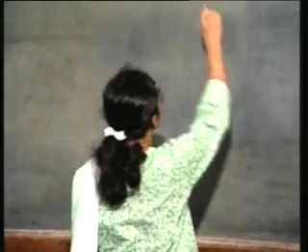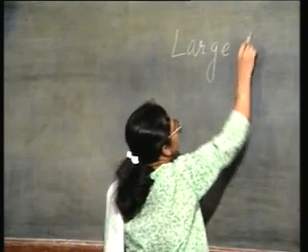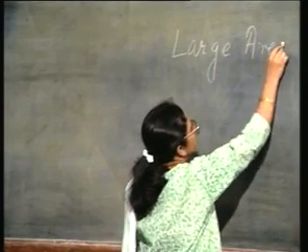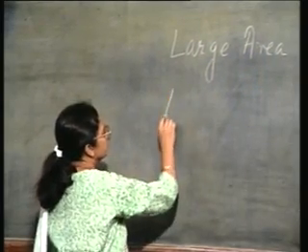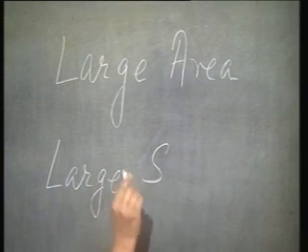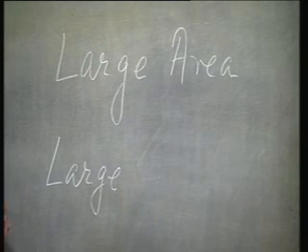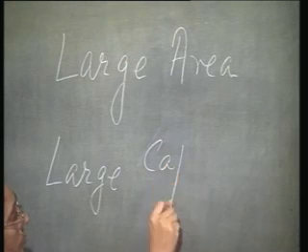So, you see basically the PN junction isolation technique has two major drawbacks. The first drawback is the large area requirement, and secondly, it has the adverse effect on the speed by having a large capacitance.